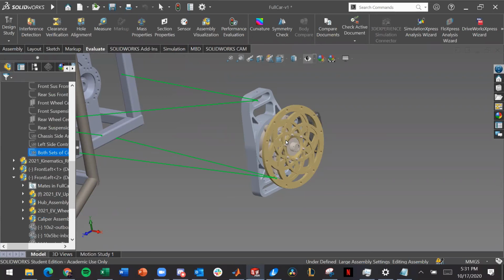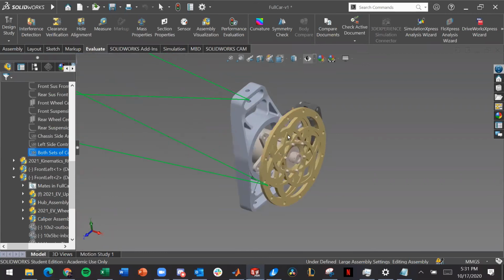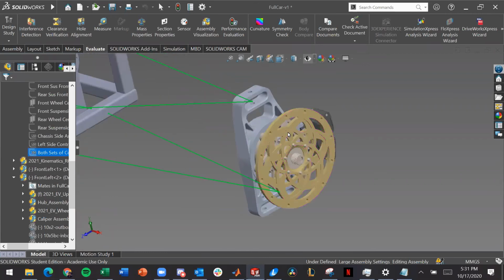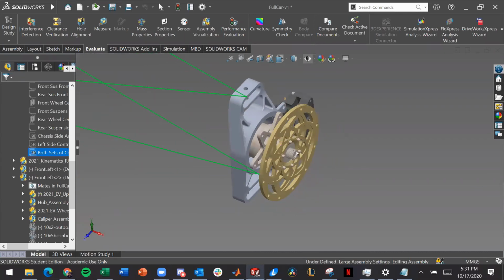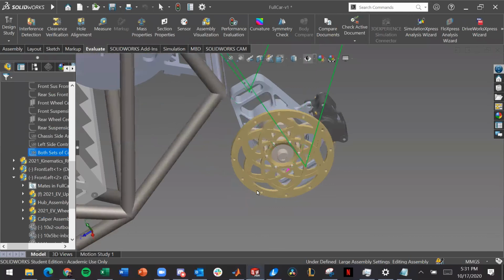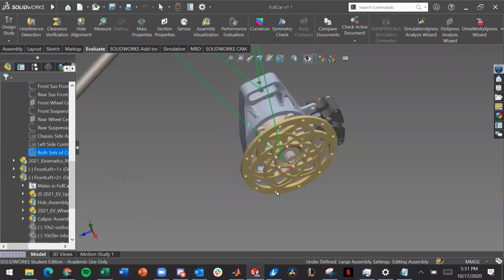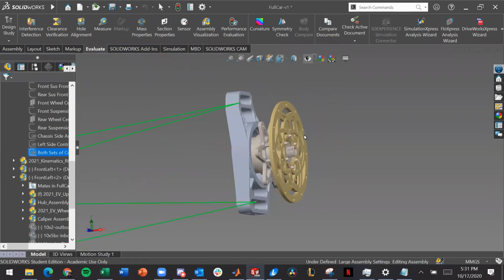We also do force calculations on every suspension component to make sure that it can take the loads that are put on it. You don't want your wheel center to snap right when you make a corner because you don't know how much load it can withstand. These calculations are basically free body diagrams and what is taught in a normal dynamics class. They're very important to calculate because they supplement FEA. FEA just shows you where the strain occurs. Hand drawing free body diagrams gets you the actual force values.